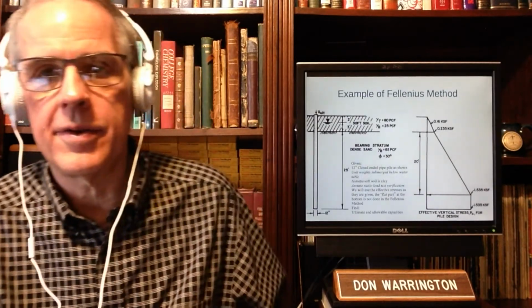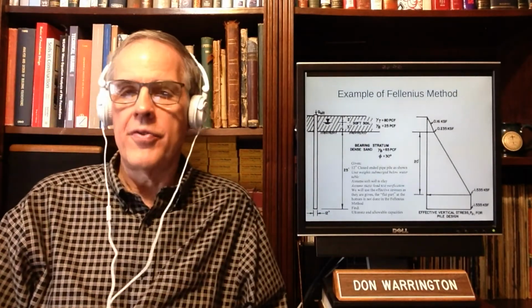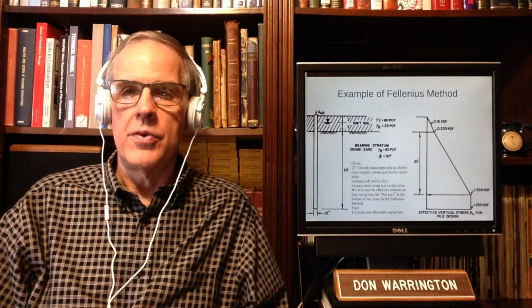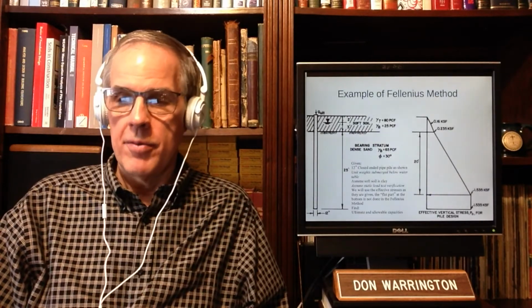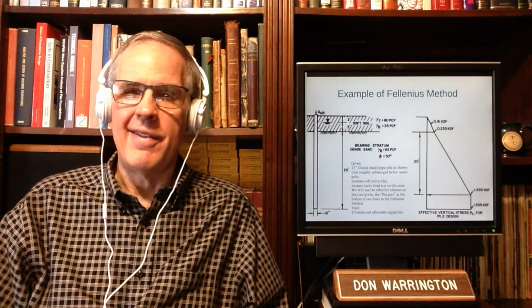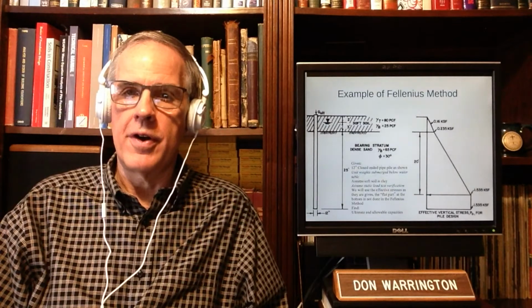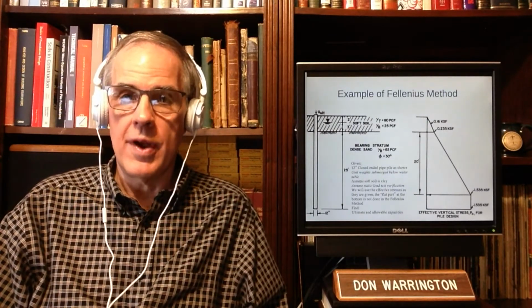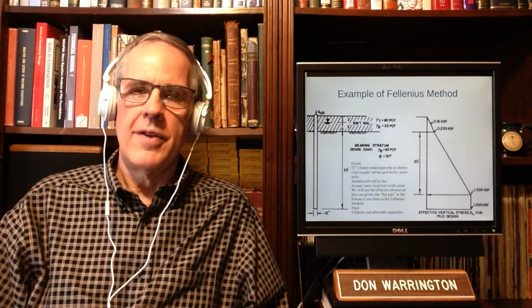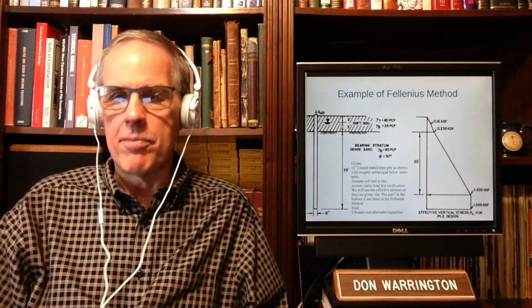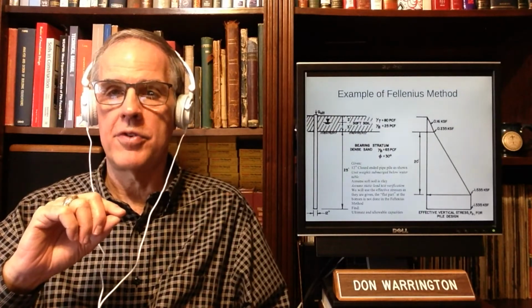And I'm going to explain how. First of all, you'll notice that the soft soil has a total unit weight of 80 PCF, 80 pounds per cubic foot. But you'll also notice that there's gamma B. What is gamma B? Gamma B is the buoyant weight, or what we normally prefer to call in this course the submerged unit weight of the soil. So if we were writing this out, I got this from DM7, I would say it's gamma prime.